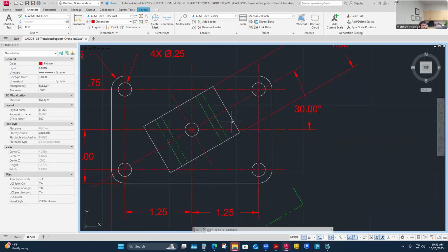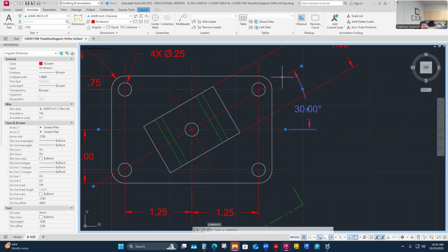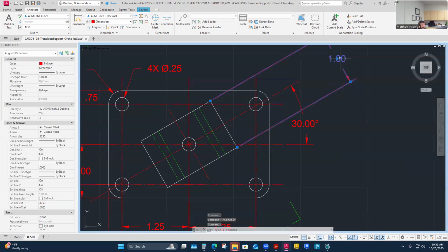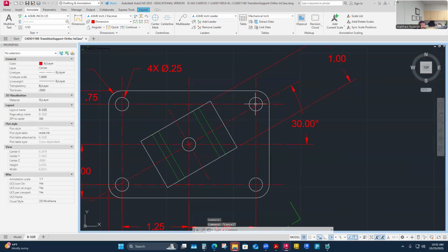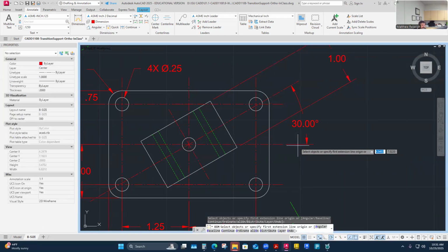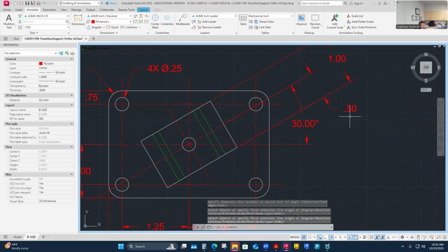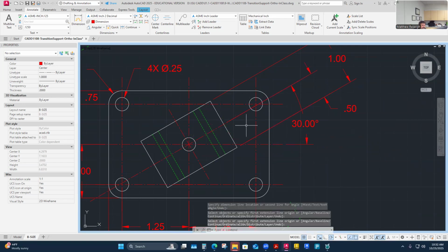And now I'm going to think about it, since maybe I'm coming from here 30 degrees to here. I'm going to put a dimension linearly here. I'm kind of building this maze back to this dimension. This is weird, I know. This dimension is, remember, just unto itself. It's not unto any critical hold, no critical datums. So if I say, well, datum's here to here, what about if I say from here to here? Still an angular dimension, but now I'm kind of coming back to a datum.